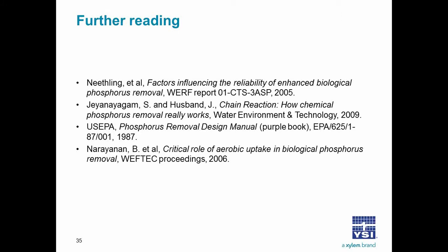But actually, simultaneous precipitation has advantages as well. And actually, there are fewer competing reactions in simultaneous precipitation, and there are a significant amount of TP present as soluble TP available for removal. So possibly a lower chemical dosage. Post-precipitation, on the other hand, is probably going to be only suitable for those that have very low effluent soluble P, and mainly the reason is, if you don't already have it, the need to add a tertiary unit process. So high capital cost.